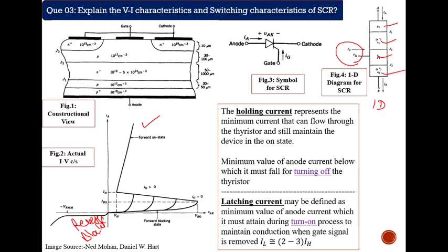So if Ig is equal to 0, then the current wave shape follows in this manner, following this red signal path, if you are following my cursor, and then again it moves into the holding current, and this anode current will follow the requirement of the DC static characteristic, and accordingly it will follow the path.